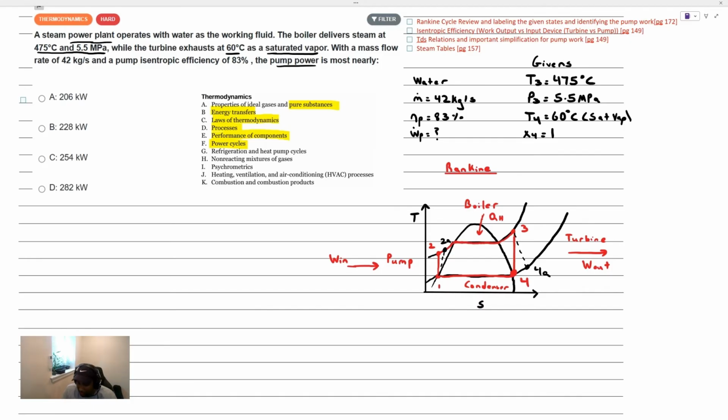of the isentropic efficiency. The isentropic efficiency is this term eta, and there is a distinct isentropic efficiency for a work input device like a pump versus a work output device like a turbine. Always think in your mind that the isentropic efficiency is always less than 100%, as you're thinking about the ideal machine versus the actual machine.